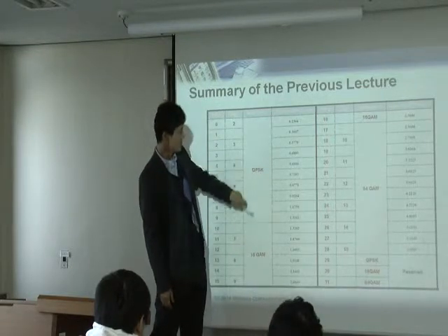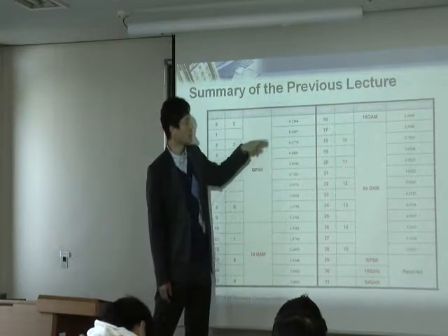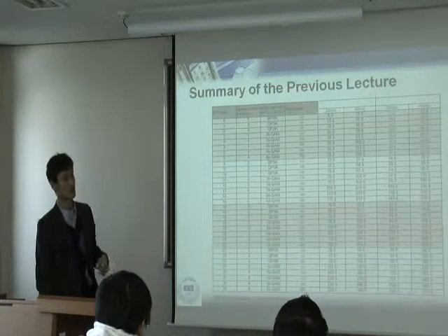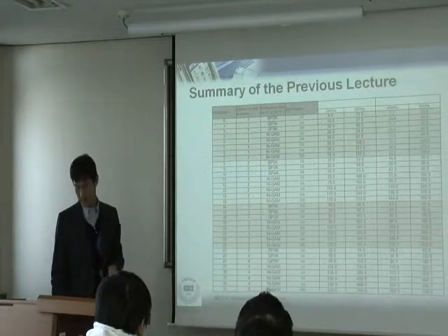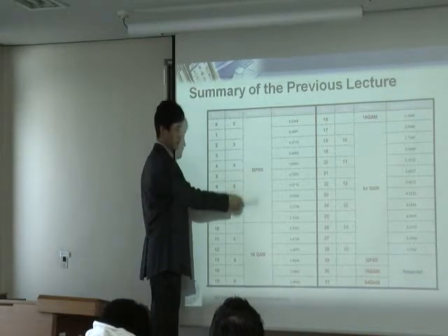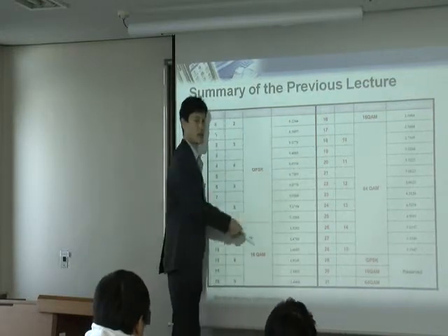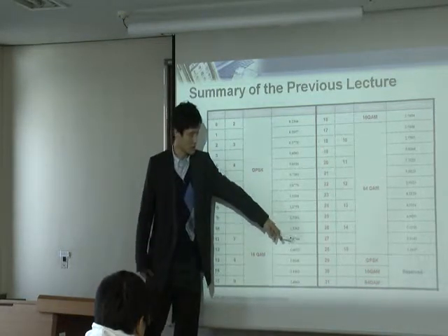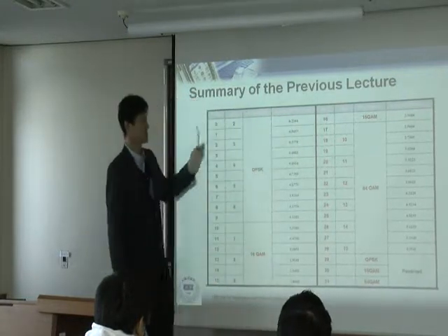You start with QPSK or any modulation with some spectral efficiency, then you calculate the code rate from these two. The code rate is not going to be half or 3/4 now. It's going to be some fractional number, some weird number for code rate. But anyway, here as an example, you see that using 3 different modulations and several different code rates, we have these many choices from 0 to 30, generally 32. These 3 are reserved for other purposes, but anyway, this is the table.